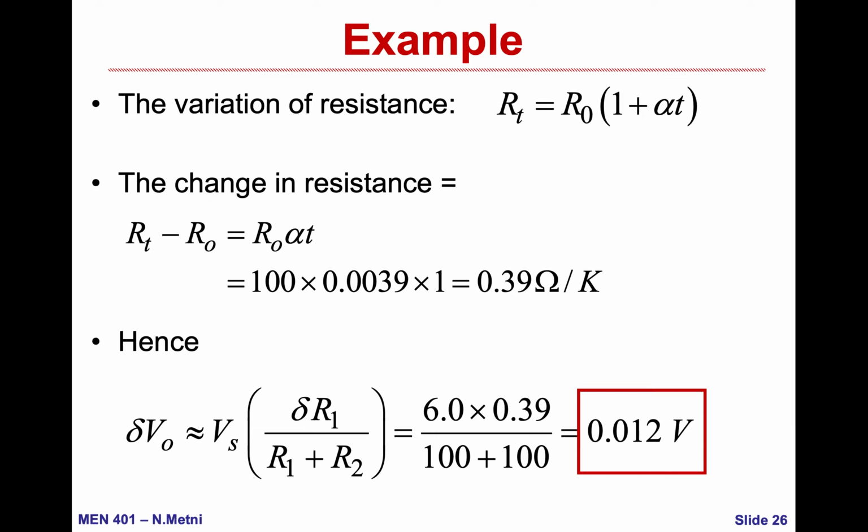So now I have a relation that will give me the temperature change with respect to voltage change. This is what I mean by conversion. The sensor ideally and initially gave us a change of resistance based on a change of temperature. However, through the Wheatstone bridge, I am having a change of voltage based on a change of temperature. This change of voltage is easily connected to the microcontroller or PLC, and then I can know from this sensitivity what temperature is being measured with the RTD.